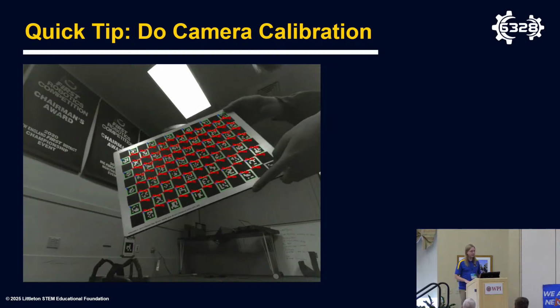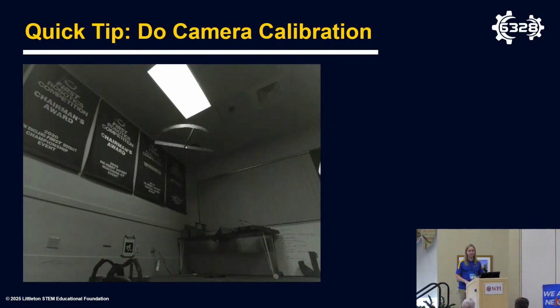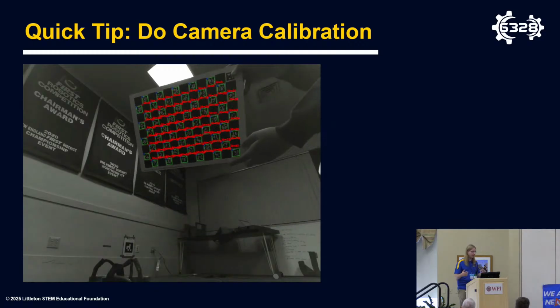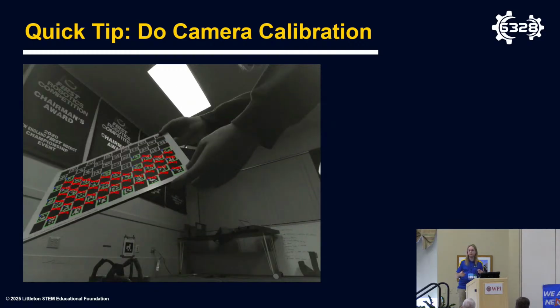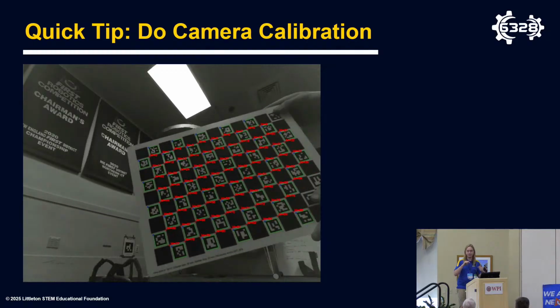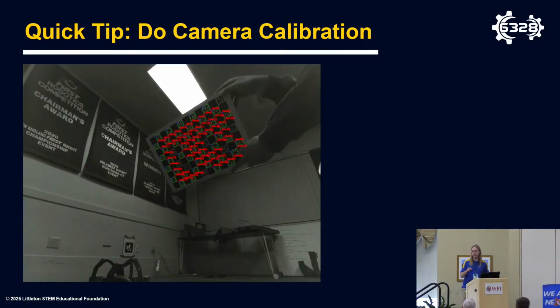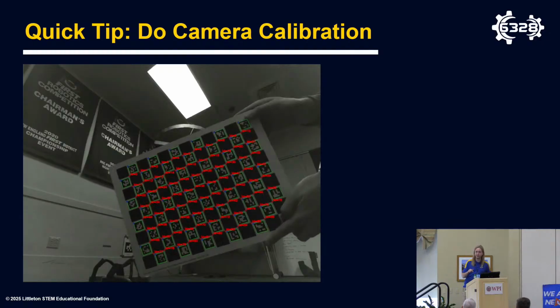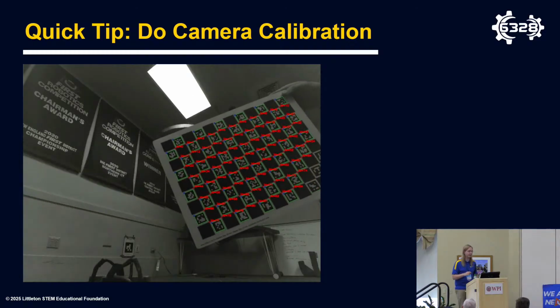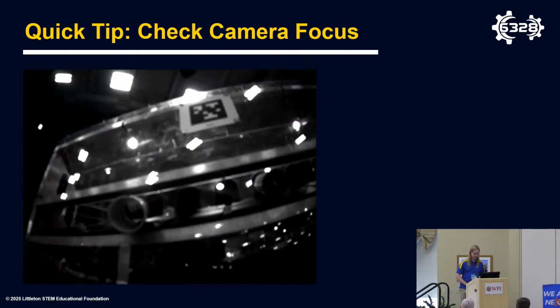An interesting anecdote: there was a time in 2023 where we had 4 cameras on our robot, all identical. We mixed up the calibrations at one point. We were able to figure out which one corresponded to which camera by simply testing them out and seeing which ones were good and which ones were bad in terms of the quality of the pose estimates. It was really dramatic in terms of what difference it made swapping out those calibrations.